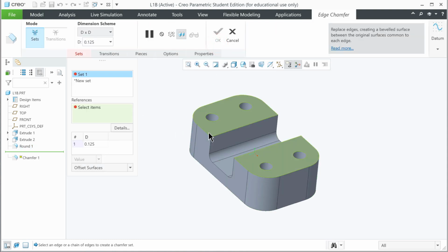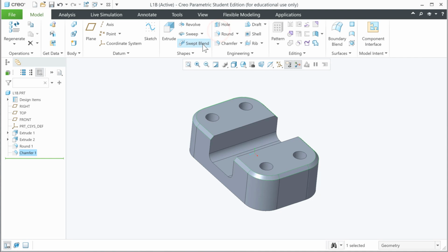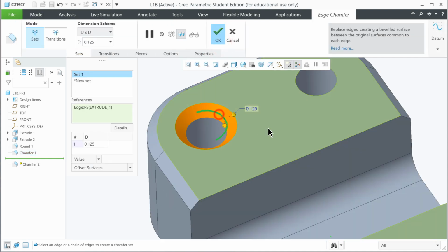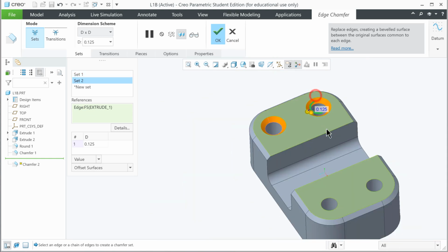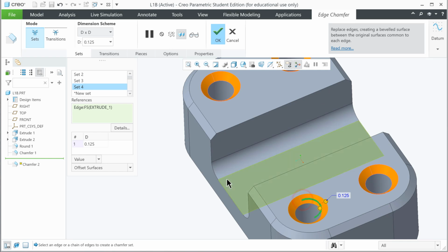Now go to chamfer, and 0.125 is pretty good. We could stick with that. Here, here. Okay. You know what, chamfer, you could also make a countersink. So you could put one here and here. Add them to the holes. And you can make adjustments to that too by grabbing those and putting values.